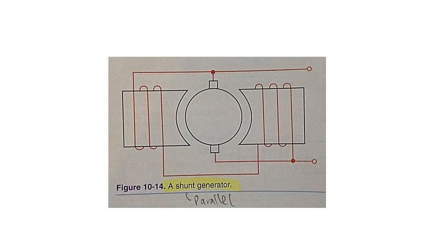All machines are designed to do a certain amount of work. If overloaded, their lives are shortened. As with any machine, the life of a generator can be shortened by an overload condition. When overloaded, the shunt generator terminal voltage drops rapidly. Excessive current causes the armature windings to heat up. The heat can cause the generator to fail by destroying the thin coat of insulation covering the armature wires.